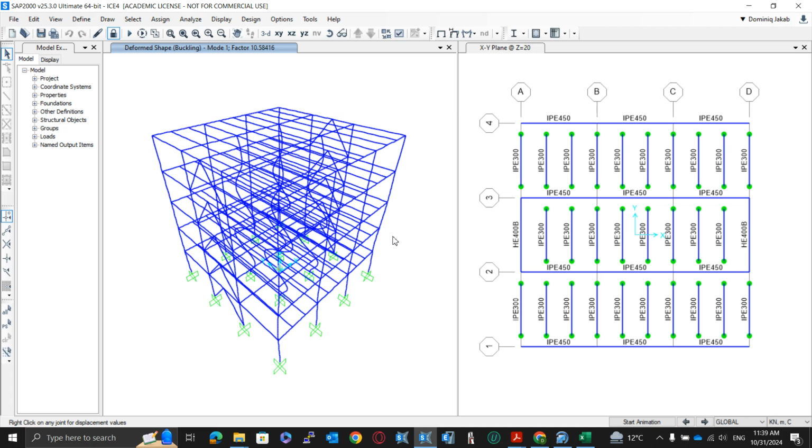The output of buckling analysis is eigenvalue analysis. It shows you, as a function of the flexibility of the elements and the flexibility of restraints, how the structure buckles. Now, is this a global or a local buckling mode? First question.